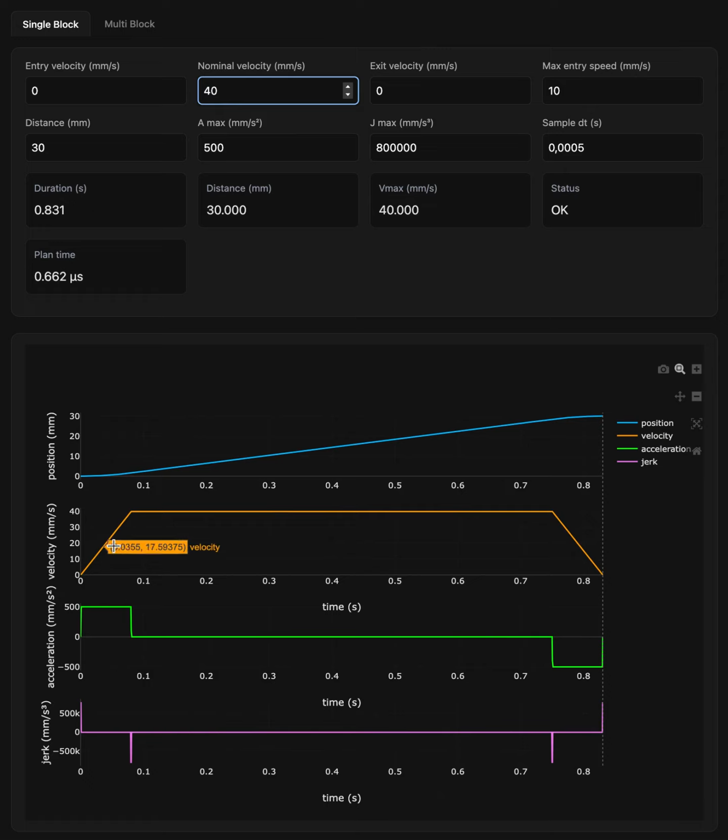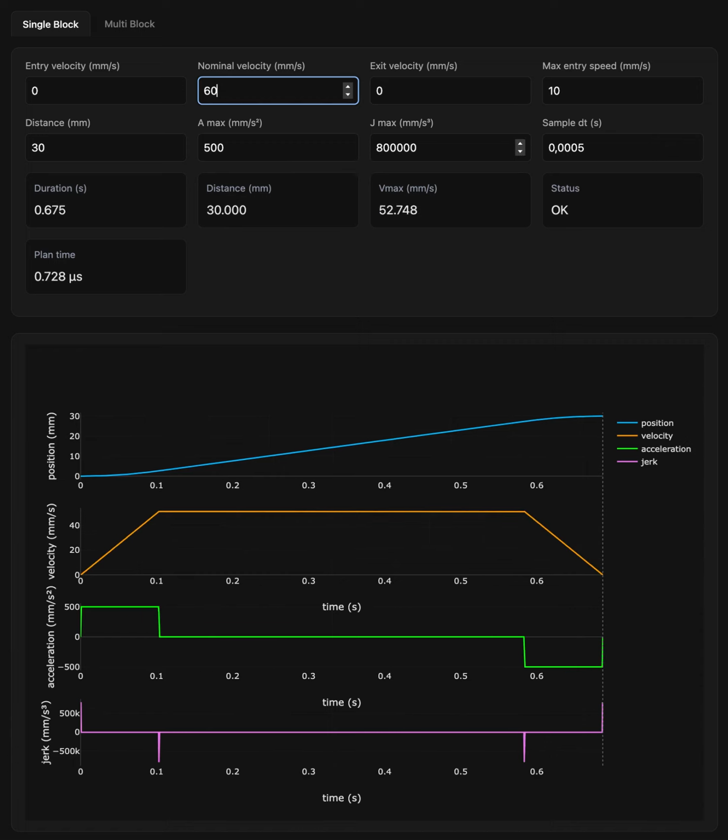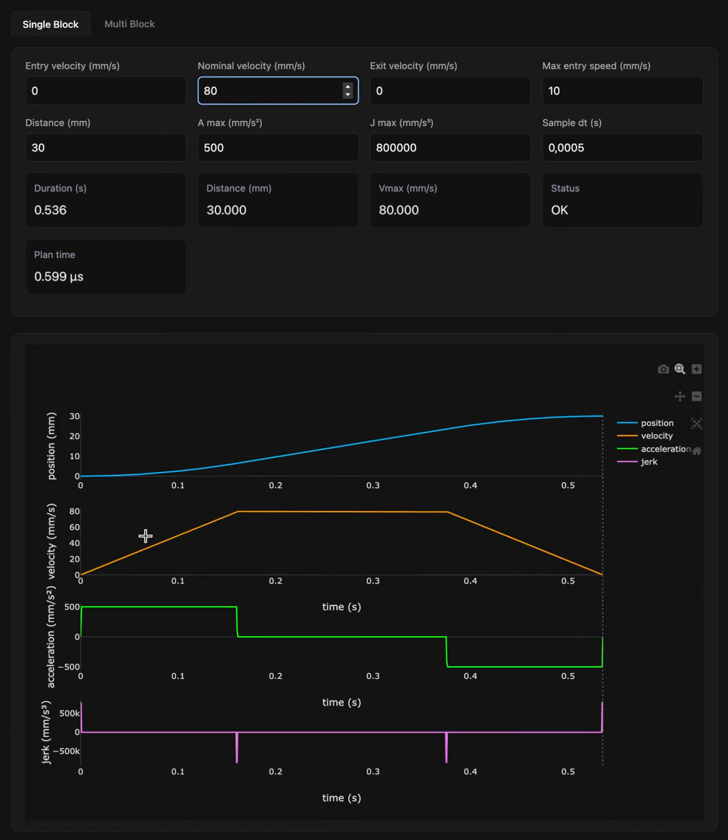Yeah, and if we feed an S-curve here, then the S-curve is going to be a lot more aggressive than if we feed it to this. And this results in very aggressive acceleration curves, and also unbound jerk curves. So we did not get rid of the problem. The extruder will still suffer, and resonances will still come back for these cases.